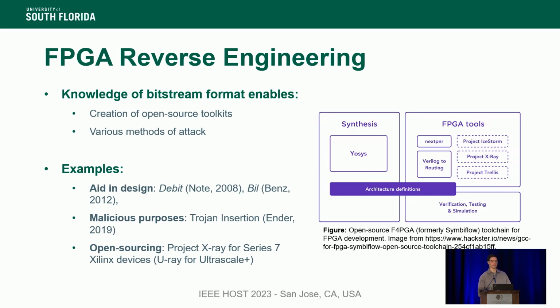So what I didn't test is manipulating the bitstream in any way and then actually testing it on the FPGA. But the Project X-Ray database has a very sophisticated set of fuzzers and stuff to determine which particular bits correspond to a different tile.